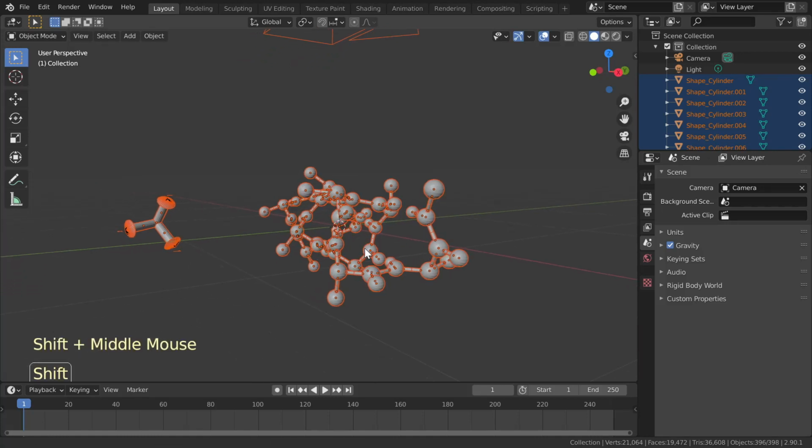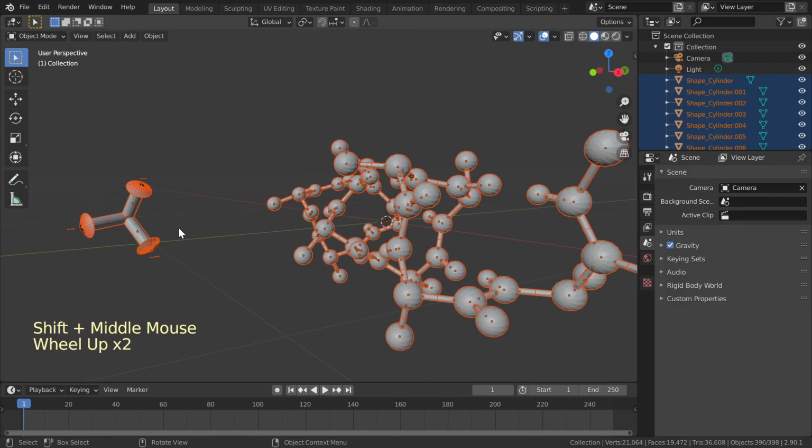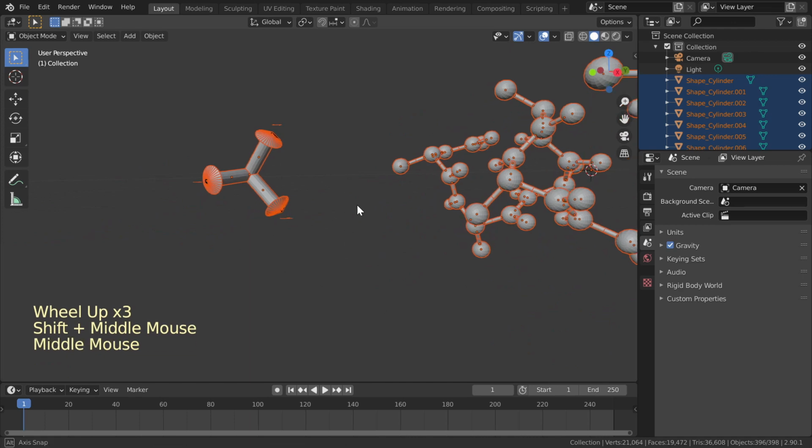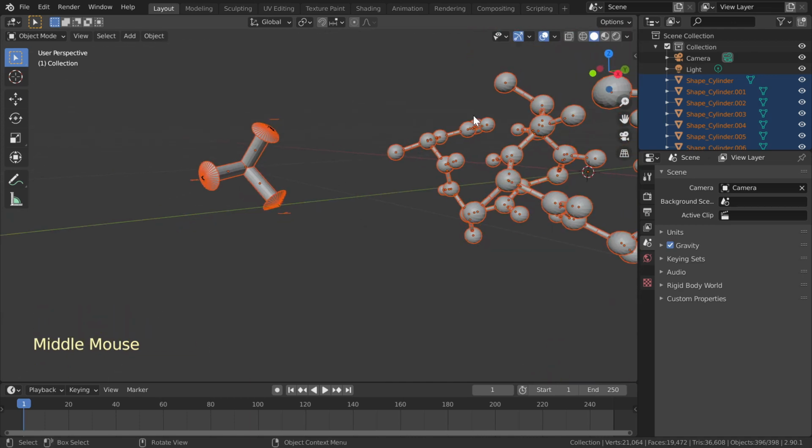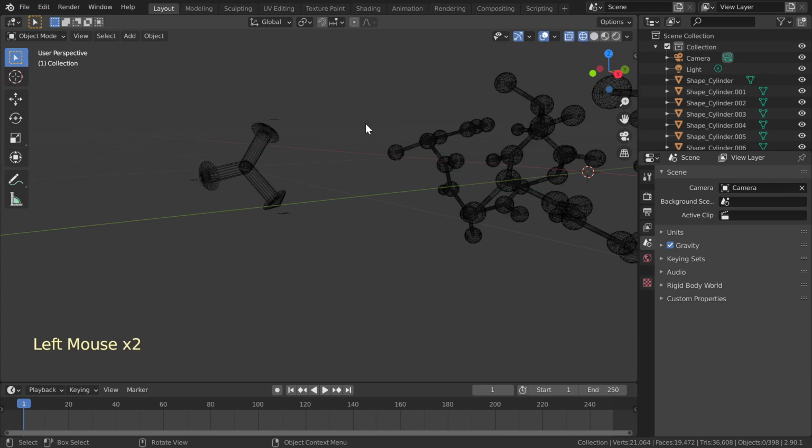Zoom close to the imported XYZ axis. Rotate view so that there is nothing behind this object. Click to empty space to unselect all. Switch to wireframe shading, otherwise drag selecting may miss some of the vertices behind the objects. Drag with mouse to select all polygons belonging to the axis object, then delete them. Switch back to solid shading.